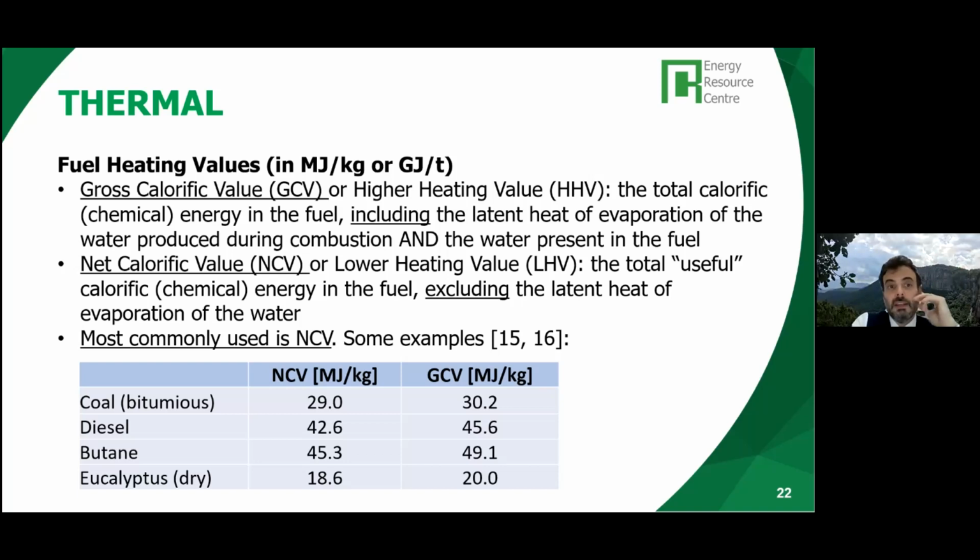Okay, so when we get rid of the water, then we can consider what we call the net calorific value or the lower heating value. That is precisely the useful calorific energy in that biomass or in that fuel. Okay, because that doesn't consider the energy we need to use to evaporate the water there.